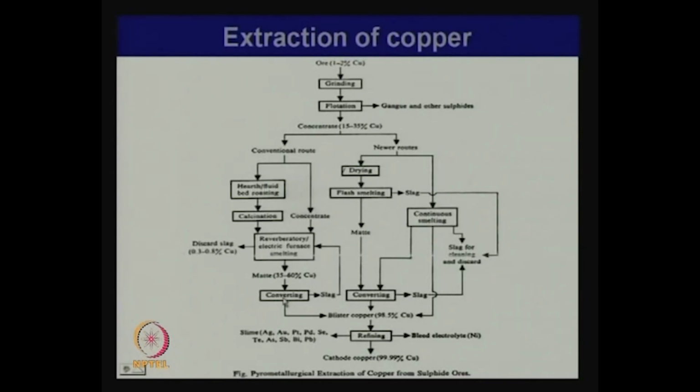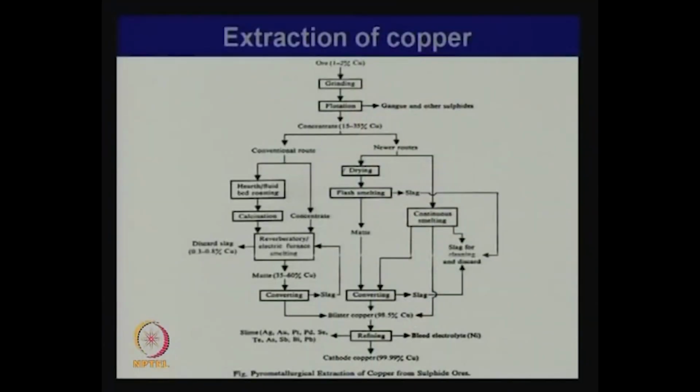You are simply oxidizing copper sulphide to form Cu2O, then Cu2O and Cu2S react to give copper, it will form blister copper. Now, obviously, we have an oxidizing atmosphere here. In the reverberatory furnace, we do not need such a strong oxidizing atmosphere, because mainly we are removing the FeO in the slag stage, but we want a stronger oxidizing atmosphere during converting. So, there are 3 stages with different PO2 requirements.